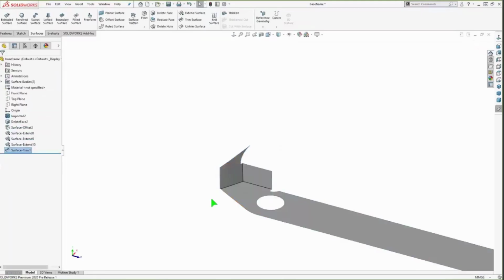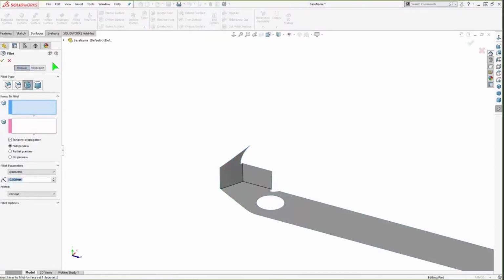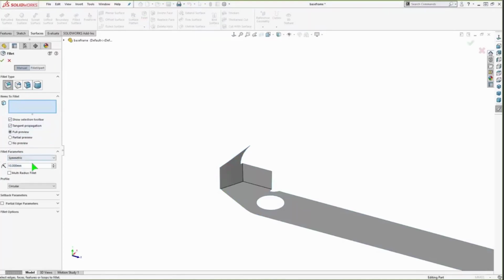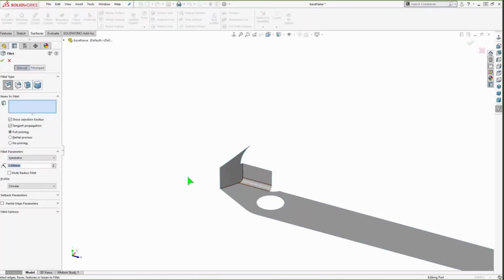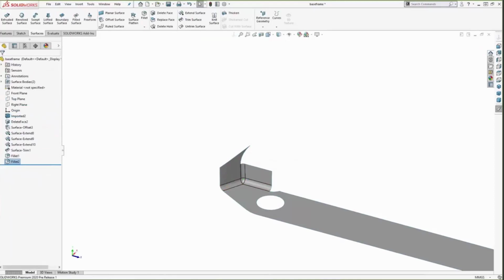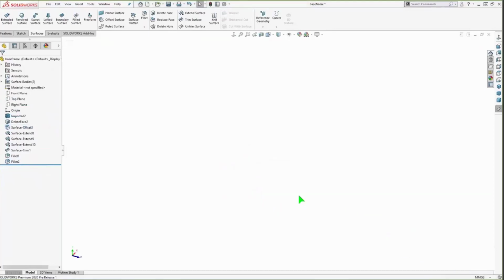And remember, I took the measurements, the dimensions of those fillets. So that information is going to help me recreate these. They're going to be edge fillets. Starting at my larger one, let's do a 3mm fillet. And the other one, that was a 2.8. And so that looks good for recreating that problem area with all the stuff around it.